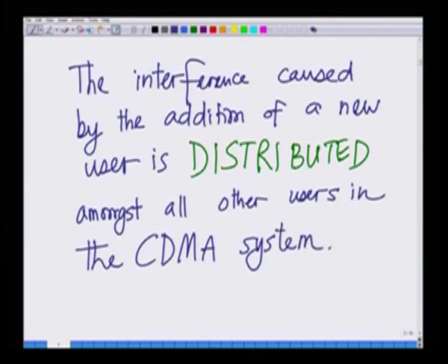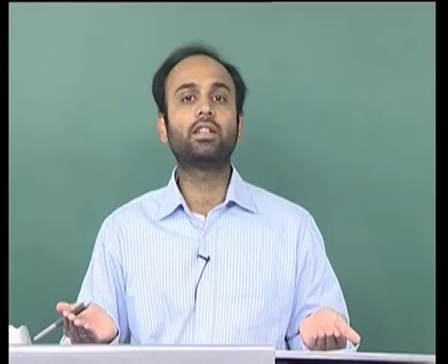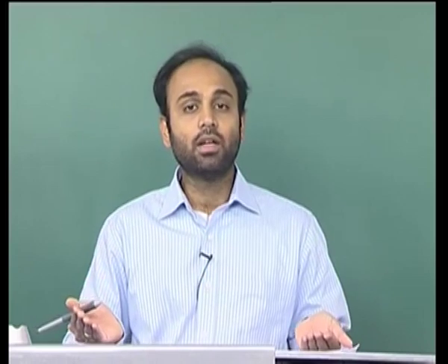Thus, the interference or the adverse effect of each new user is shared equally by all the existing users in the CDMA system. So the interference caused by the user is shared equally amongst all users. This leads to interference distribution. Hence, this leads to graceful degradation.